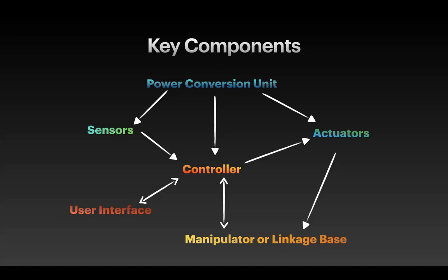So there are batteries in different voltages. Let's assume your robot has a 12 volt battery, right? But your wheels are turned by a motor, no? And this motor is actually 9 volts. So now there's a problem, right? If you provide 12 volts to a 9 volt motor, then the motor might burn, right? This is a big case.